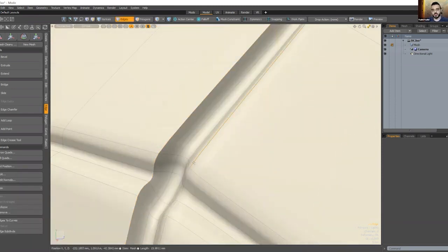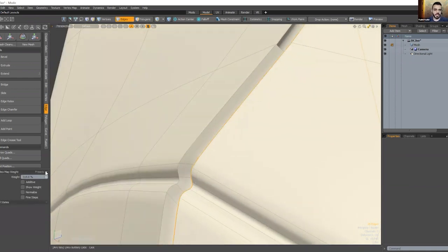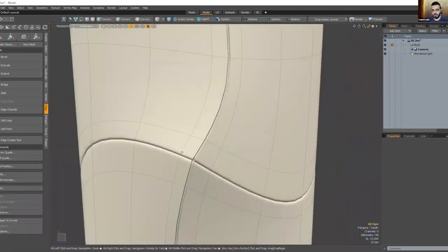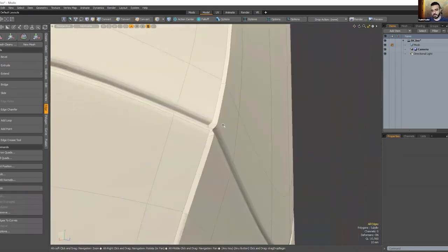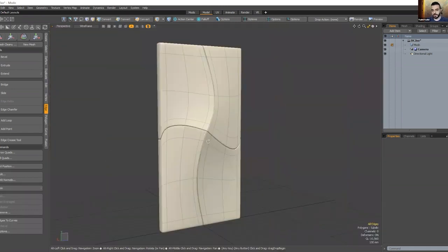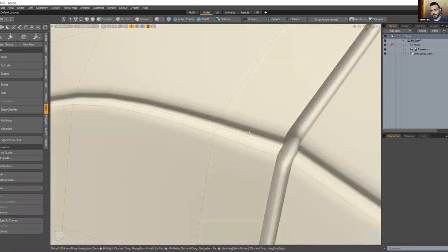I'm also going to double click on this and do the exact same thing. Shift W, which is to add the weight, and then adjust the thickness of it. I guess again, I was going to do 100, which is great. And that will give me a very nice creased edge here. I guess I can do this on the other side.